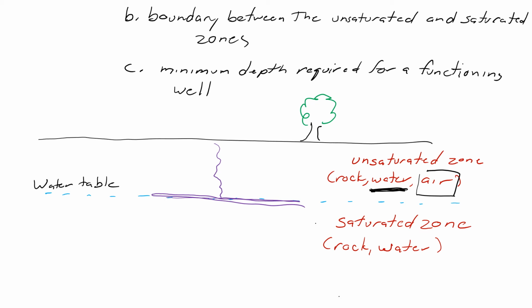The other thing, if you've ever spilled gas on your driveway or some surface, even your hands, it evaporates pretty fast, doesn't it? That's why it feels so cold. If you spill it on your driveway, it evaporates really quick. So it has to have air to evaporate into, right? Does this gas have air to evaporate into? In the pores, right? So what will happen is this stuff will sort of volatilize, it'll evaporate and go into the pores in the rock and soil, which makes it almost impossible to clean it up.